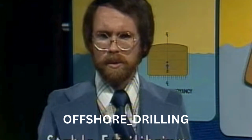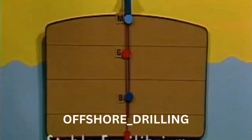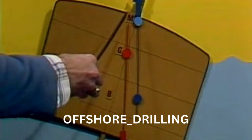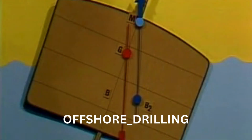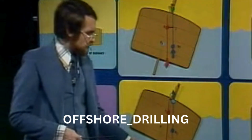First is stable equilibrium. This is positive stability, or a definite tendency of a vessel to return to an upright position at small angles of heel or tilt. Here, point M is higher than point G. This allows a righting moment to be set up when the vessel is tilted. This causes the vessel to return to its original upright position.